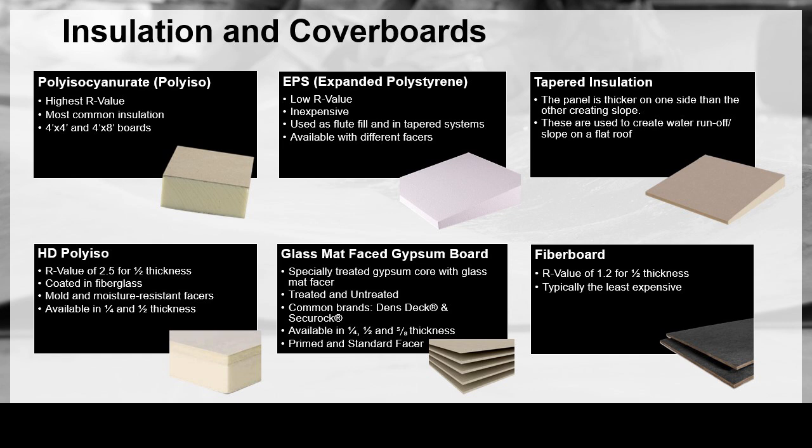So just to recap, because I know that's a lot, almost like a fire hose, polyiso is what you're going to come across. There's tapered to add, or you could use EPS as a filler with a cover board, or just the cover board, and then you're off.